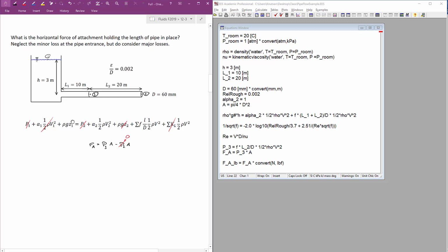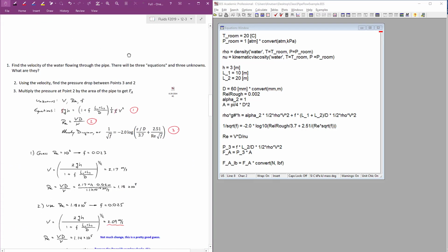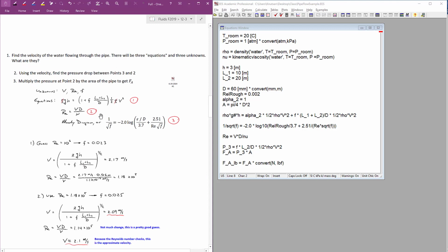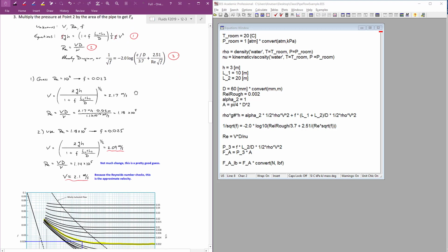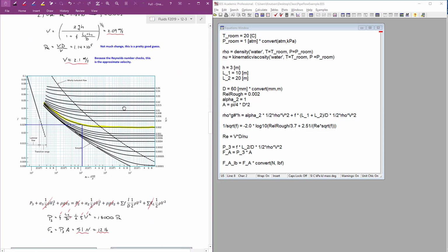This is the method in which we would solve it. The way we'd work through it with students: use this equation, come up with the friction factor, come up with the volumetric flow rate, and then we'll figure out the pressure at the fitting. So it's a pretty typical fluid mechanics problem.